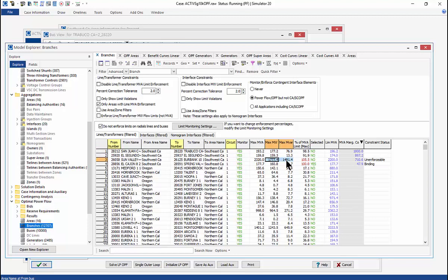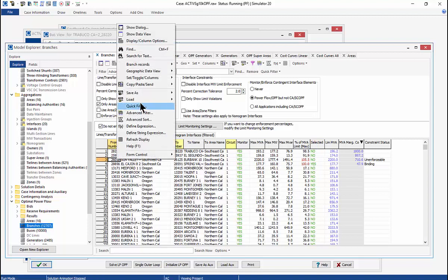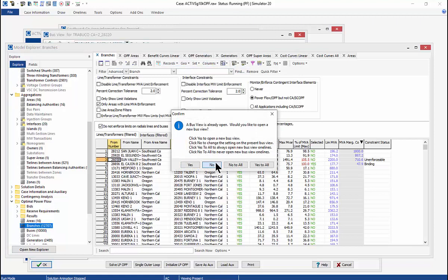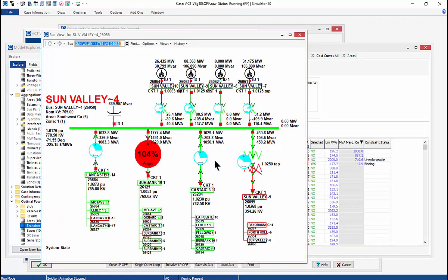Actually, this one's a little bit unusual right here. It seems like the power factor on that line is kind of low. Most of them are pretty high, so the megawatts is pretty close to what the MVA is. This one is quite a bit different, and there's almost as much megavar flowing on it, so it's close to a 45-degree angle. This one's not too bad, but it's worse than the other two. So you might look to see if there's a transformer tap issue with that. I don't know in this one what we've got going on.